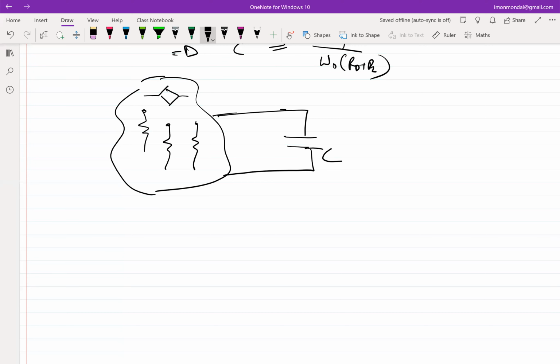So what is the algorithm? What should I look for? R out for the DNS setup. Okay. Somebody said RTH somewhere here. Right. So essentially, very good, what we are trying to figure out is the equivalent Thevenin output resistance looking into the network. The reason I said everything inside is resistive is because this impedance will always be resistive if everything inside the network is resistive, which essentially means that I should be able to replace the stuff inside the network with RTH, and we'll have a capacitance here, and all we have to ensure is that